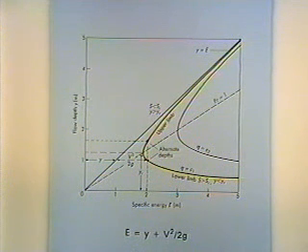And what happens if you change something, and a good example would be maybe changing the bottom slope, the longitudinal slope. If we were in a laboratory, we could imagine looking at some sort of a flume or a channel. In our laboratory here at A&M, we've got such a thing where it's a variable slope, and you can jack up one end and change the slope. And of course, when you make it steeper, the water flows faster, you get a higher velocity and a lesser depth. And in some ranges, a change will result in a bigger change in the velocity head than in the depth. In some other ranges, vice versa.